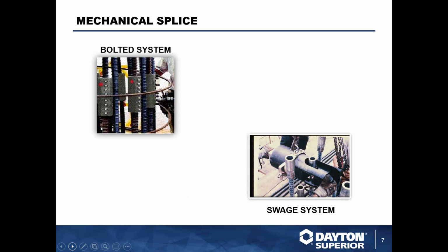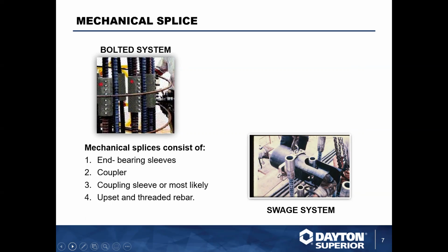Barlock produces a bolted connection coupler that uses shear bolts that penetrate the rebar and cause the rebar to engage some rails in the bottom of it to gain the strength of the rebar. So it's a non-lap splicing rebar connection. And once the bolts shear off, you know you have a permanent connection. Your connection is actually completed.